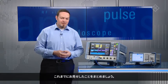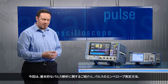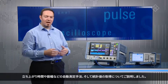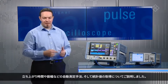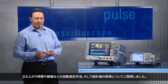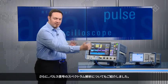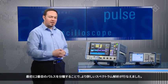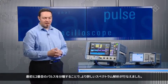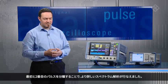So let me summarize what we have seen here. We have seen a basic pulse analysis. We have shown how to make the envelope of a pulse, how to apply automated measurements like rise time and amplitude. We also get statistical values of our pulse. At the same time, we were doing a spectrum analysis of the complete capture, but then we also did an additional spectrum analysis of the first pulse and the second pulse to get more information about my pulse.